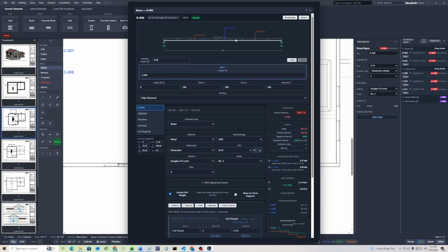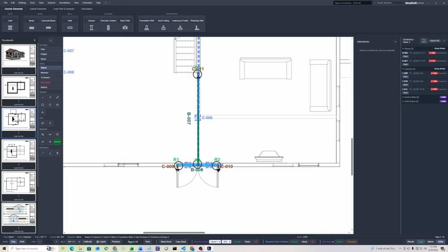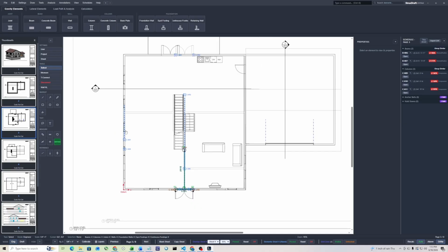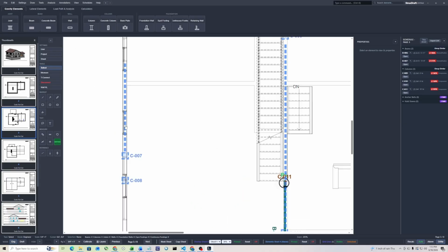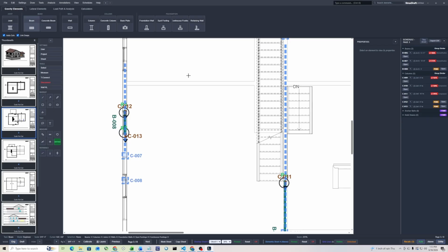Likewise, we can open this so we see the 3-point loads from the beam and the 2 columns. Good. So we see that we get this wall load over this header. So let's go and add a beam here, the auto columns. We'll connect that up. Connect.